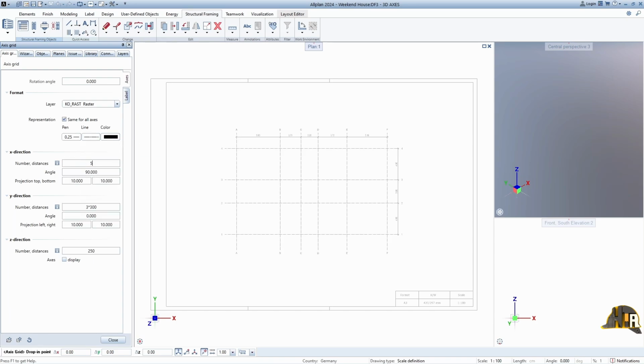For the X direction, we will enter the values 560, 270, and 220, respectively. The semicolon sign is very important because it actually tells Allplan that a value has been entered. An ordinary comma sign is used to enter a decimal value. So, if you enter values with commas, Allplan will give you an error sign. Now we continue entering values 372 and 518.